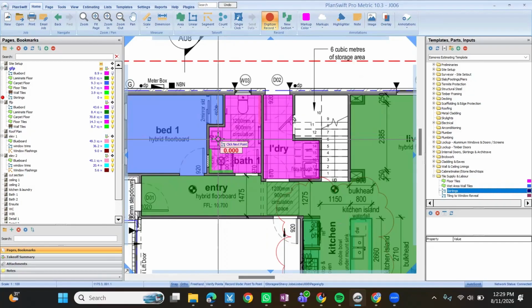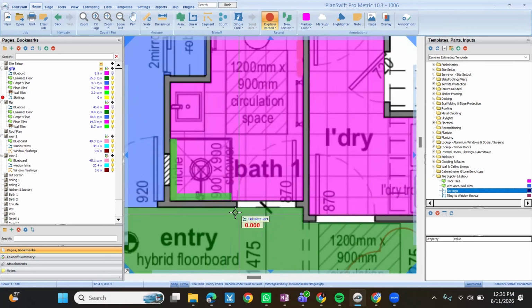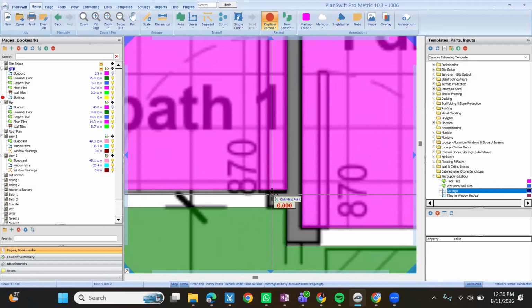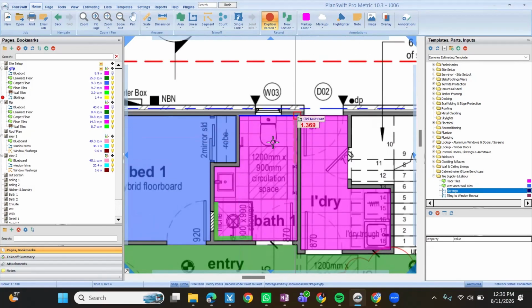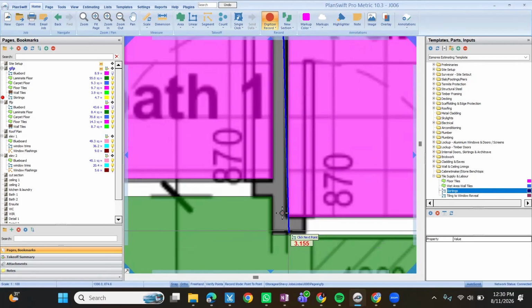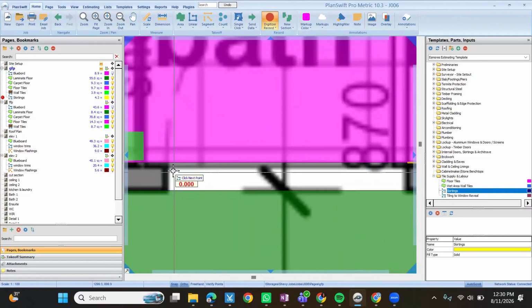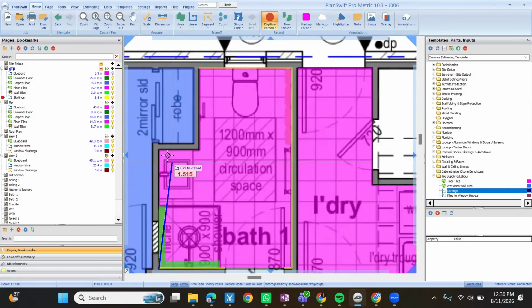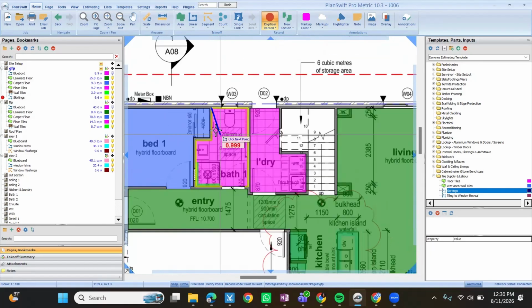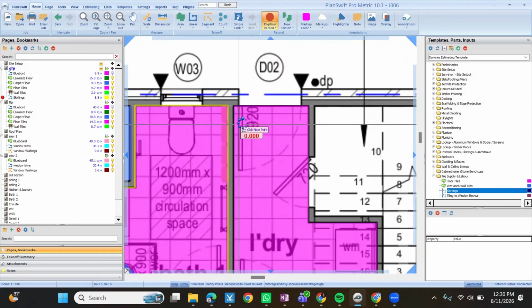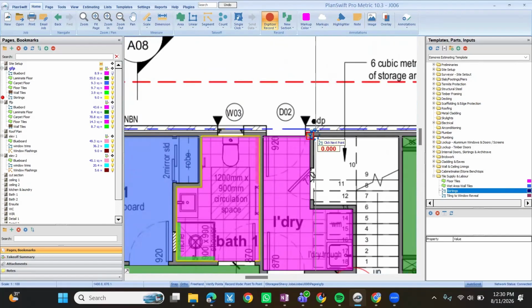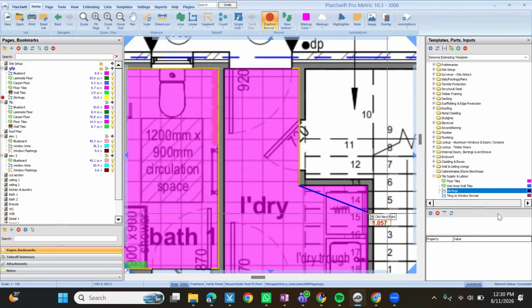Again, guys, it's really important that you have your own template so that it's easier for you to do the takeoffs. Unlike if you don't have a template, sometimes it just takes time. For the skirtings, always remember not to include the openings. If you're dealing with cornice, you can consider the openings, but for skirtings, I don't recommend putting skirtings on parts where there are openings.